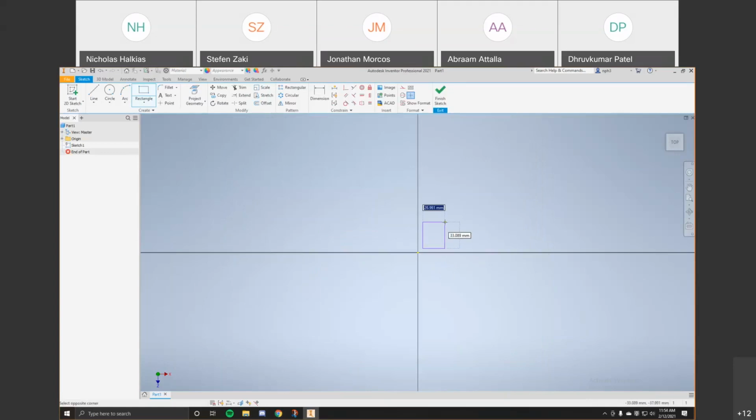And now what you can do is, if you can see at the top that the highlighted units, so that's going to be our width. So that's going to be 30. So we can just type in 30, and then you press tab, and notice how the units get locked. So now those units are locked at 30. I can only edit the height now. And then we're going to type in 60. And then you can just press enter, or you can hit tab again just to make sure it's locked. Everything's locked in place, and then just press enter.